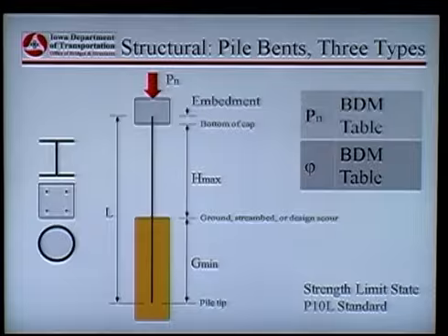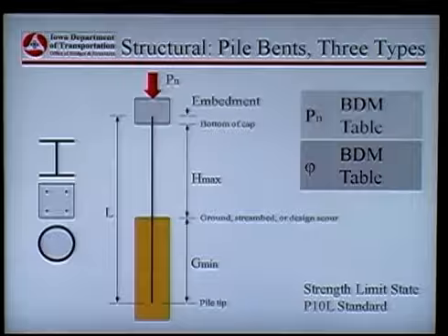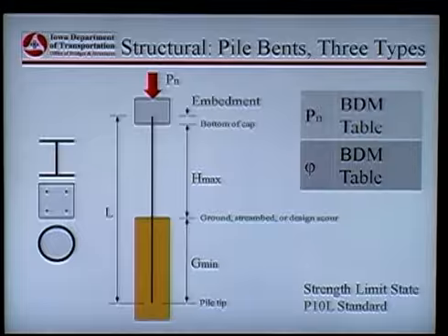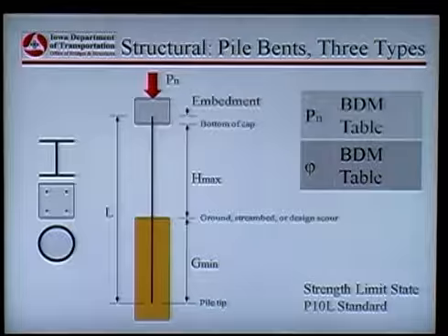In the case where we have kind of pre-designed pile bents, we set up the P10L sheet, which used to be a P10A. We've set that up so that you can just design for a vertical load. We've set the limits and everything so it covers an ordinary amount of moment and so forth in the pile. We've set that up for the H-pile, pre-stressed, and pipe piles.